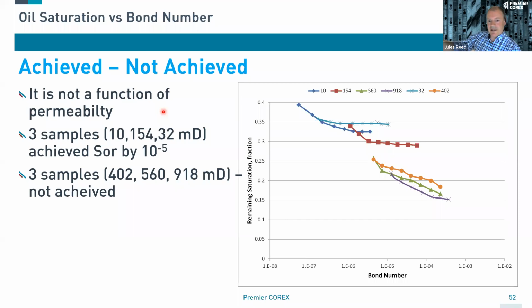As you begin to get lower wetting numbers, so positive 0.4, 0.3, 0.2, getting closer to 0, the more you come away from strongly water wet, the higher the force that you're going to need to apply in the imbibition process. So very often, for most liquid hydrocarbon reservoirs, you're going to need to apply some force in imbibition in a capillary pressure curve to get to true residuals. Good question, thank you.